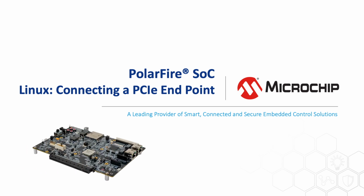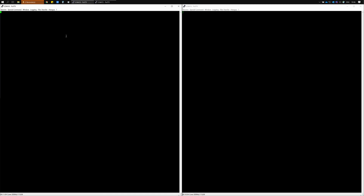In this video, we're going to connect a PCIe endpoint and test it using Linux on the PolarFire SoC Icicle kit. We have COM10 open here, which is MSS MMUART0 for HSS messages, and COM15 open on the right, which is MSS UART1 for Linux console messages. We've connected up an NVMe drive on the PCIe header of the Icicle kit, and let's power on the kit now.